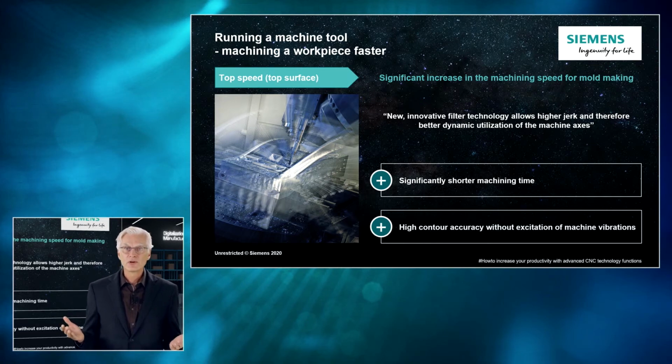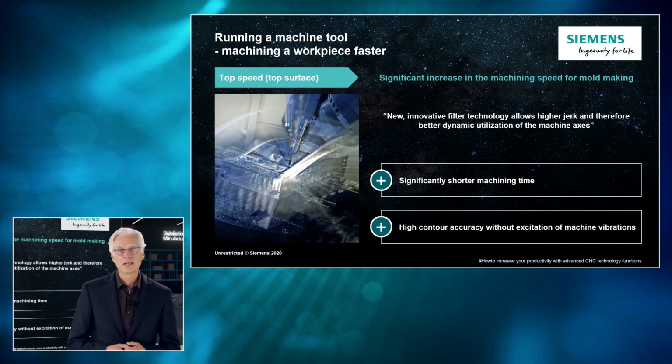For example, 3- and 5-axis simultaneous machining, such as the machining of freeform surfaces, need a high surface quality. The CNC programs for these are generated via a CAD/CAM chain and consist of huge point clouds. Experience has shown that it makes sense to check the quality of the geometric data on the controller with an intelligent algorithm and to clean up the data in the sense of a homogeneous, meaning shiny, workpiece surface.